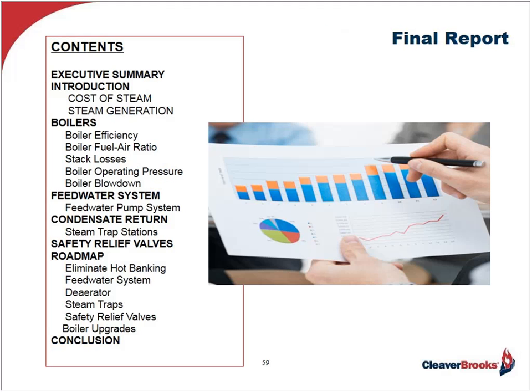Then, following this cursory discussion at the completion of the assessment, the specialist will return to the office and prepare a formal report for all that was witnessed, including the discoveries, and then a path forward for that particular client. It will contain information such as you see here, which was taken from one of our clients, but I'm sure other reputable assessors will prepare something similar. So you start with the executive summary, kind of an overview, get into detail about the boilers, how they're performing, feed water system, the safety relief valves, and then a roadmap or a path forward for attacking those cornerstones.